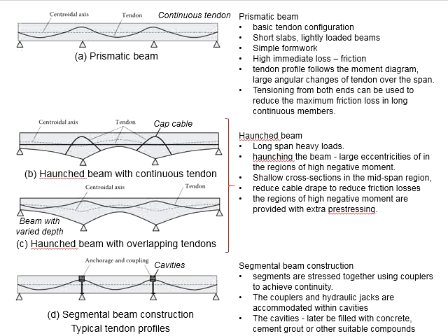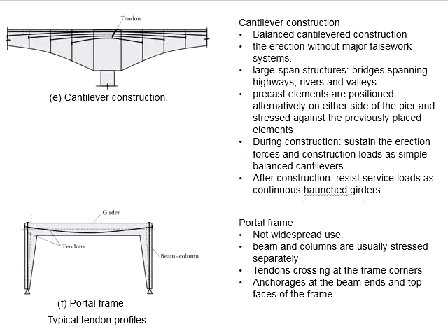After you have done pre-stressing, the cavity can later be filled with concrete, cement grout or other suitable component in order to cover the tendons. By doing this, you will have a much shorter effective length for the frictional loss, and this will subsequently reduce the frictional loss. Next, we look at another construction method, which is known as the cantilever construction, or it is referred to as the balanced cantilever construction.